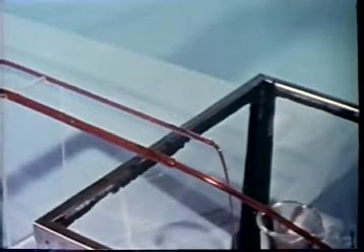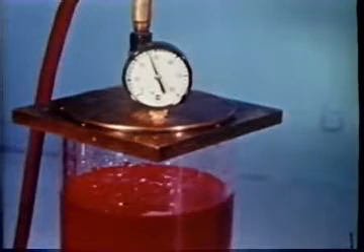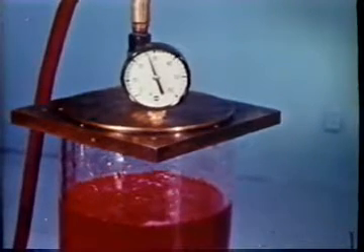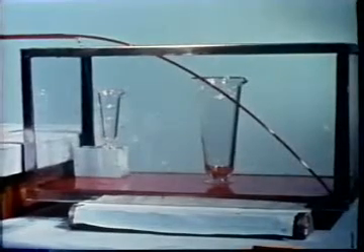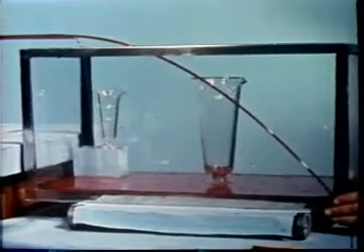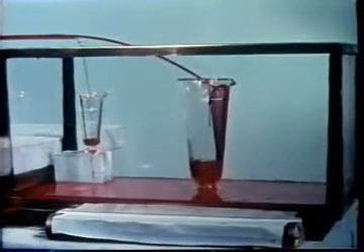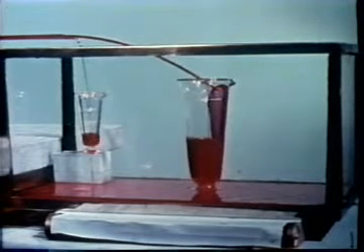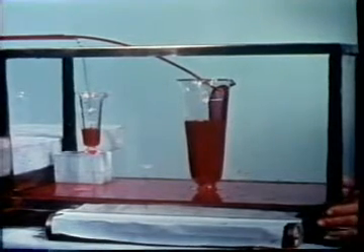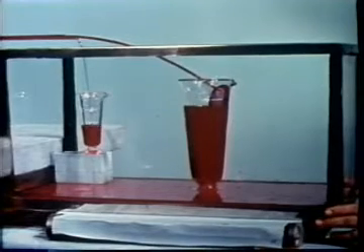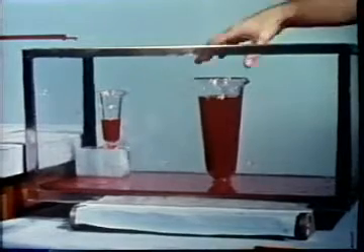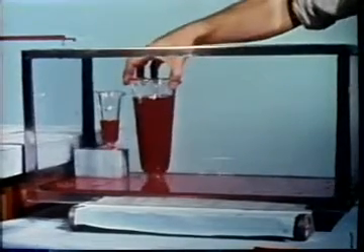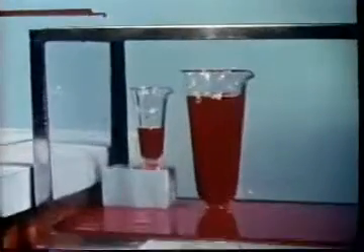The bore of one of these tubes is twice as big as the other, but they have the same length, and the fluid is driven through them at the same pressure head. Calculation shows that the discharge from the large tube should be 16 times that of the other. The receptacles are marked at 1 ounce and 16 ounces.